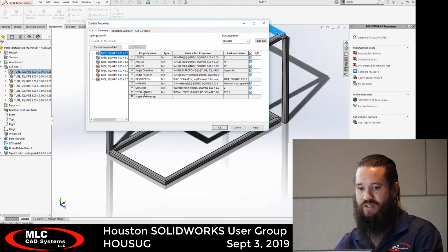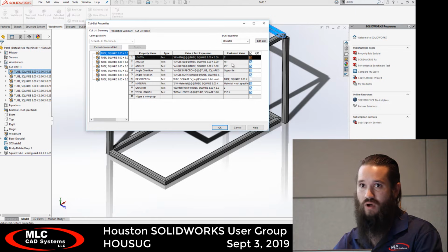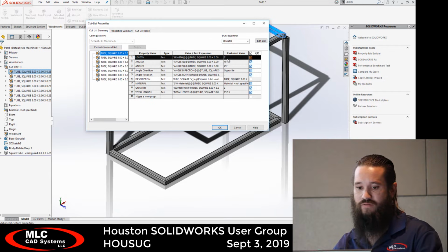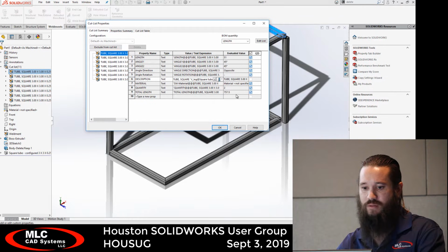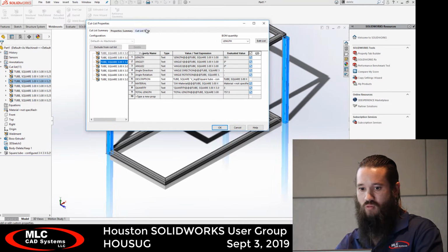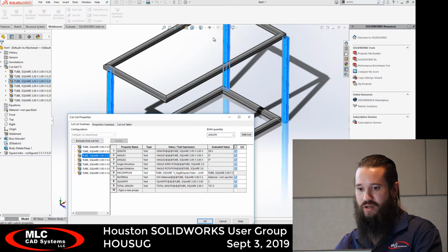So we can customize this to have a default length. If we don't have any special end treatments or whatnot, we can call that out in our cut list, let our fab know without a detailing view. Anything else just comes default, description for the profile and what you customize here in your list. When you go through your list, you'll see that it'll automatically identify identical members.